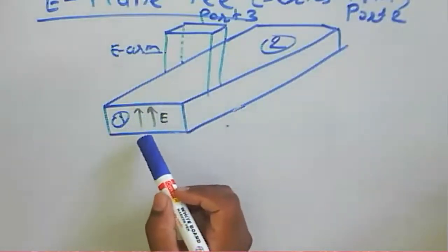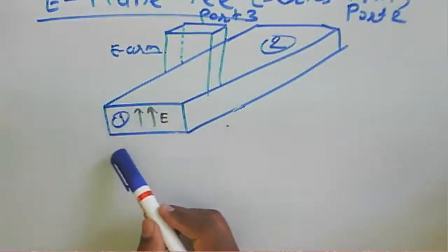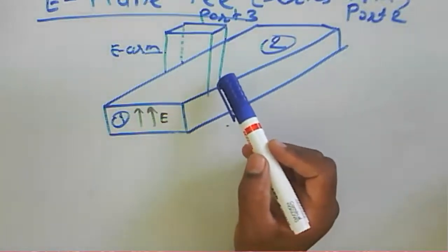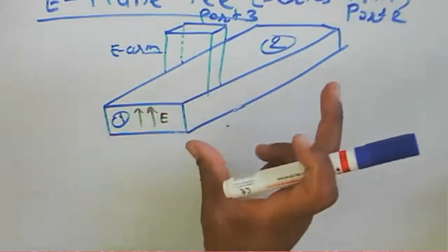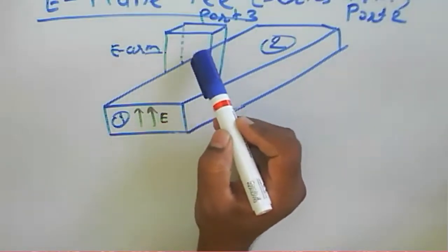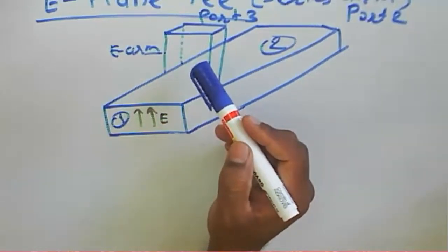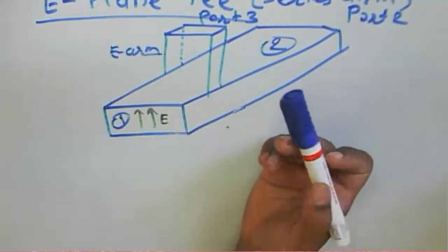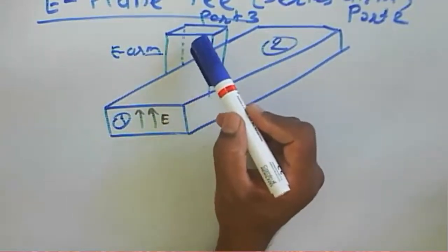And another thing is that if the input to port 1 and port 2 is the same in phase as well as amplitude, in the same phase, then the power at port 3 will be 0, meaning the output at port 3 will be 0. The condition is that it will combine power in both cases, with out of phase or in phase. But if the output at port 1 and port 2 is in phase, then our port 3 output will be 0.